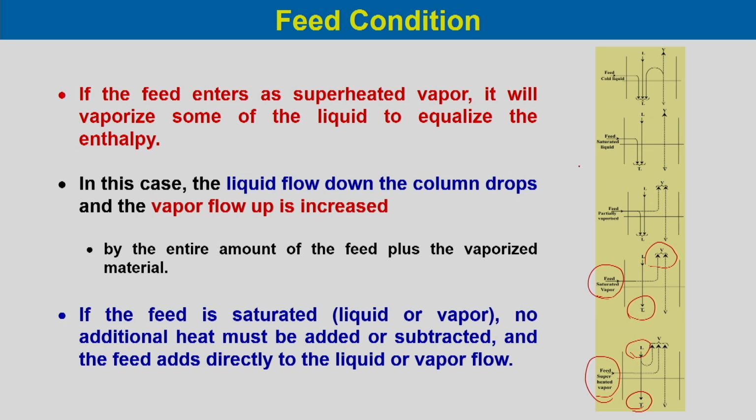And similarly, if you take the saturated liquid, in that case your liquid does not need to be heated up, and so the vapor flows as it is, and the vapor flows above the feed tray will not change. However, the liquid flow will increase by the amount of the feed flow.